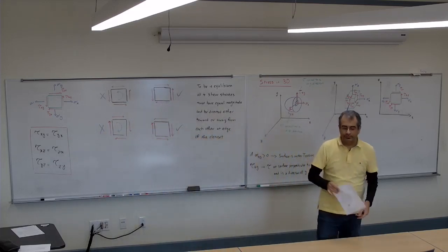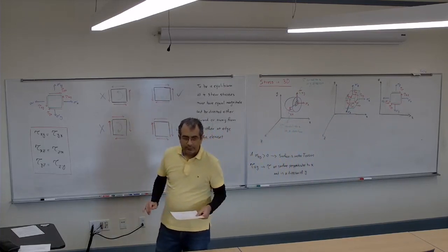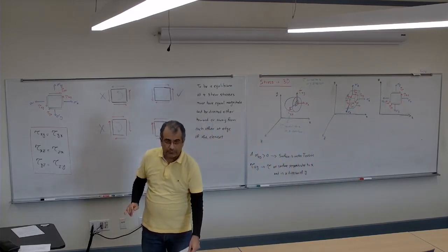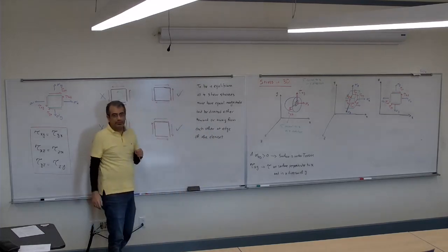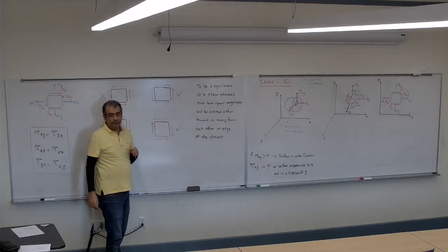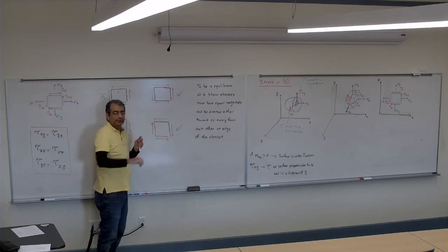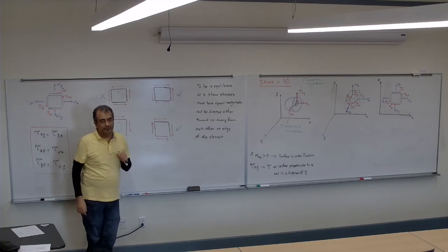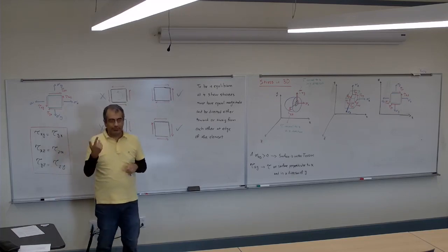Do the shear forces at the top and bottom have to point in different directions from each other? Yes, okay, because otherwise the sigma fx would not be 0. If both of them are in the same direction, the element would move in that direction. So they should be away from each other to make sure sigma fx and sigma fy